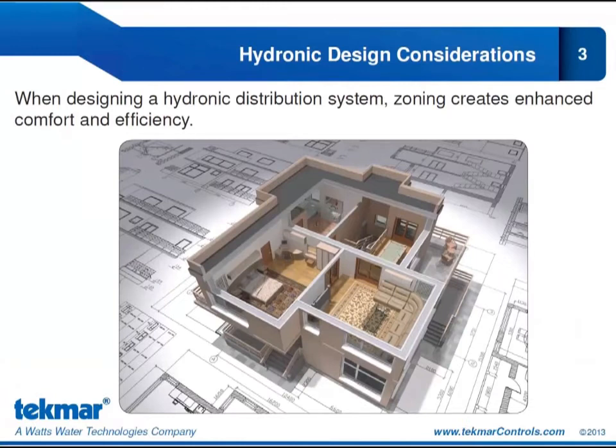Let's first take a look at the hydronic design considerations. So of course, when we are talking hydronic design, one of the major benefits is the ability to zone a space. As we've talked about before, every room in a building is going to have some unique heating and cooling needs, and that will depend on its location, if it has exterior walls or not, how much window area it has, what the occupancy is like.